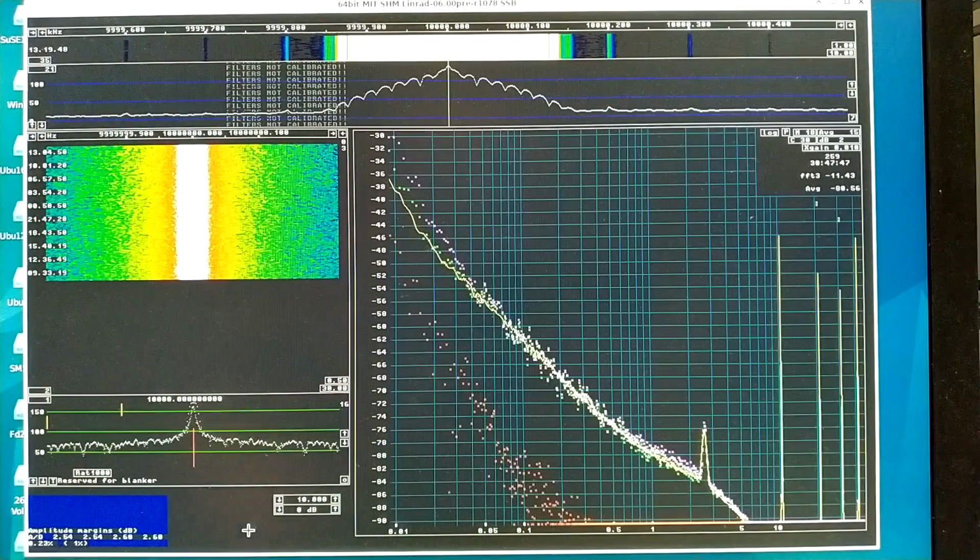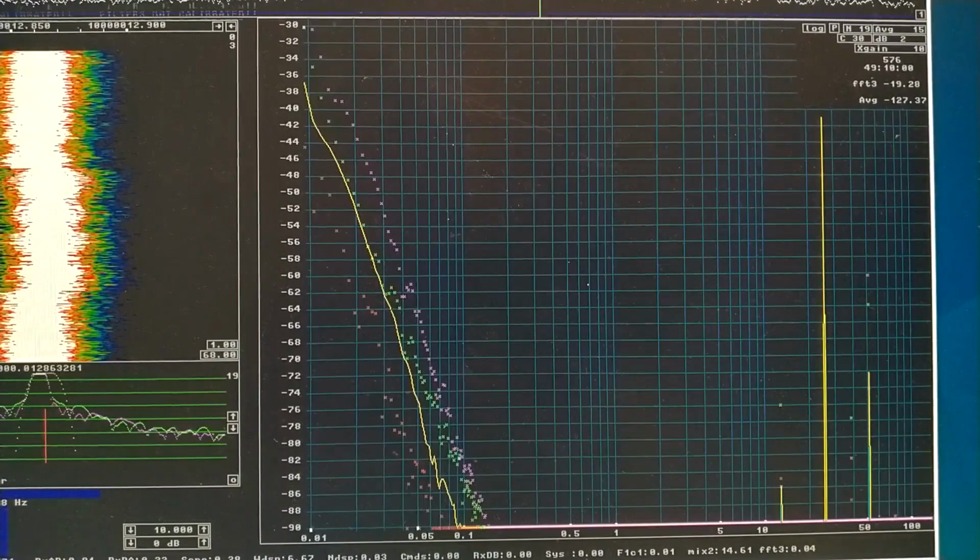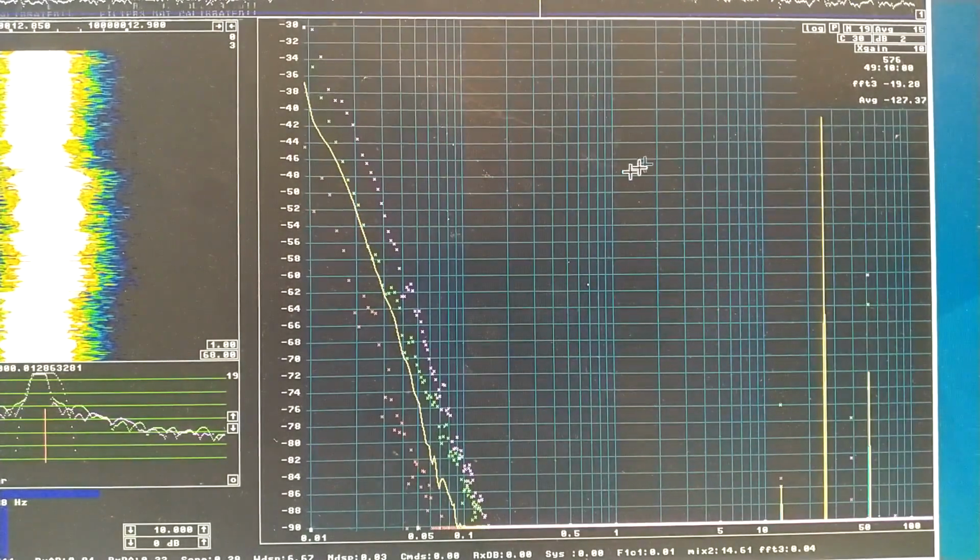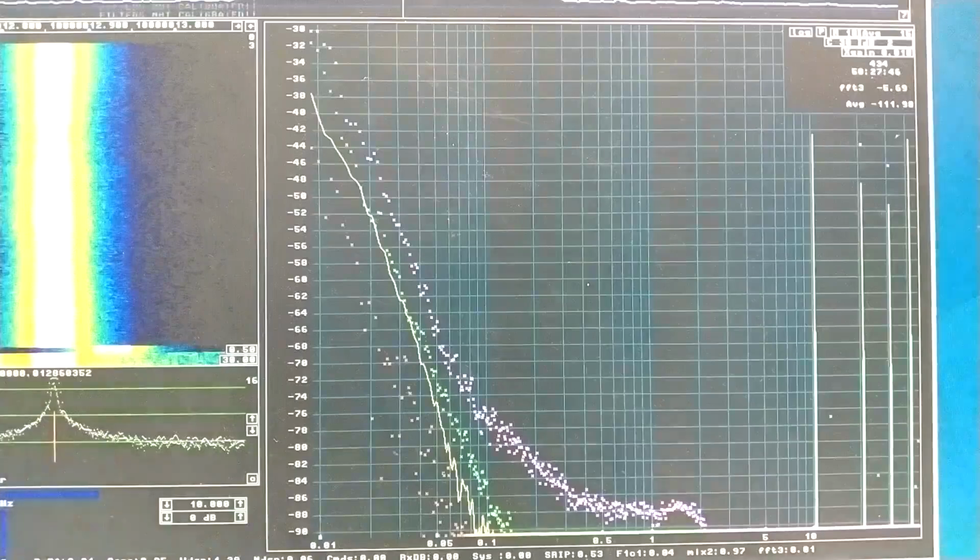and reasonably fast probably. I have connected my Wenzel oscillator and run it for a long time, 49 hours now. And I can see at 0.01 hertz, it looks like minus 39.5 perhaps, here. I have also been running, this is with the sound card.